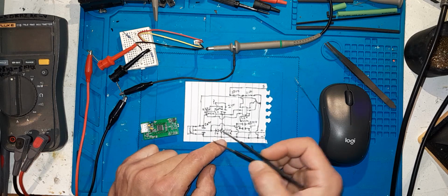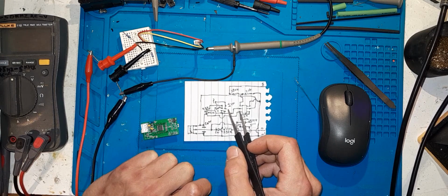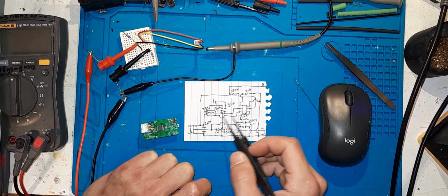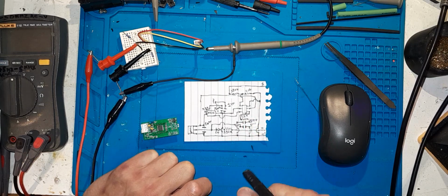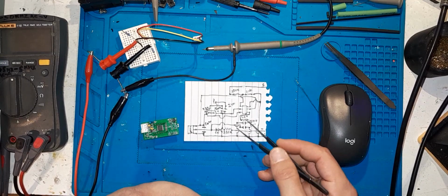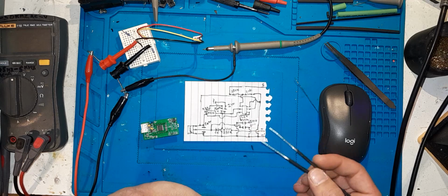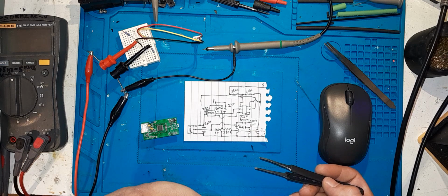No, that doesn't go to the op amp. What I will do is I'll have a look at what pin this is that the op amp does go into, or whatever this is. I'm starting to think it's not an op amp just because of the way it's wired up. It's got a snubber network going to ground on this one pin here, and then it's not powered from a reference voltage.